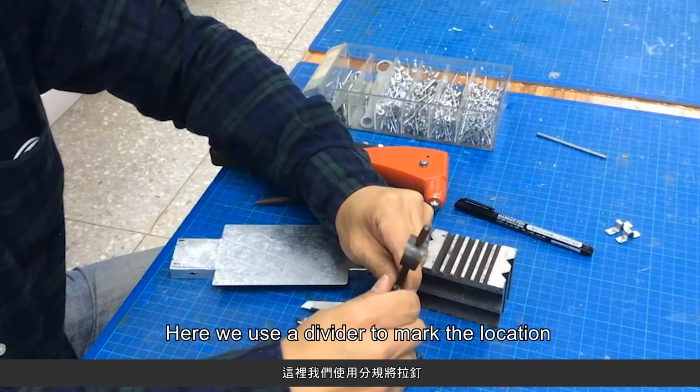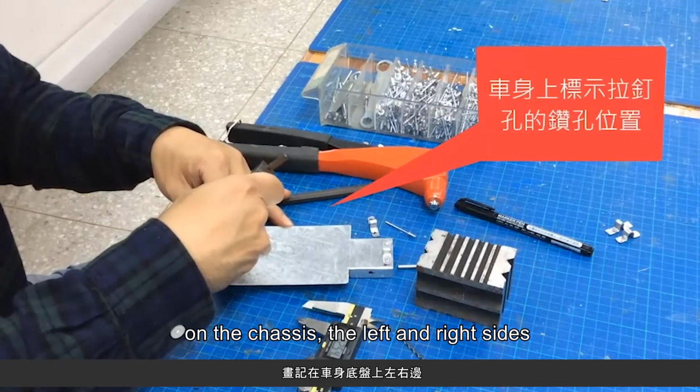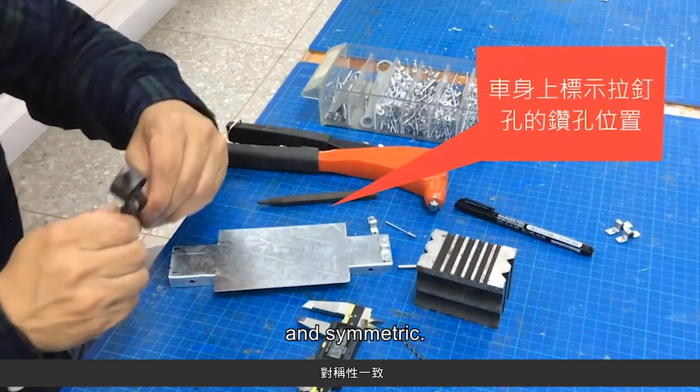Here we use a divider to mark the location where we want to drill the hole on the chassis. The left and right sides should have the same depth and symmetric.